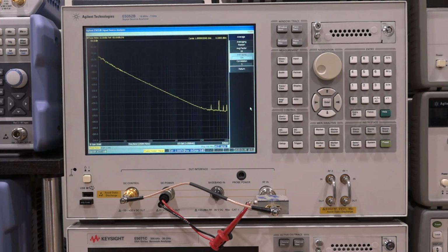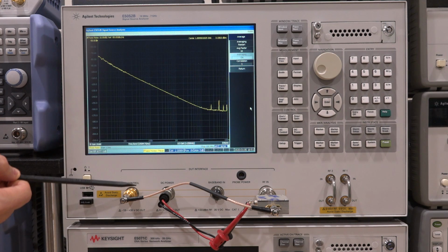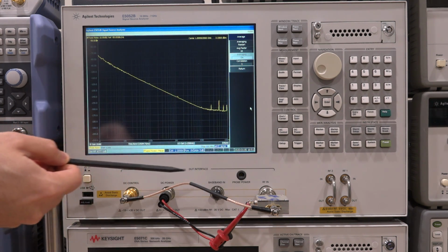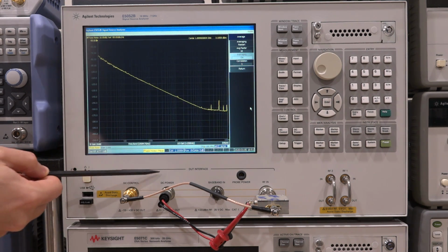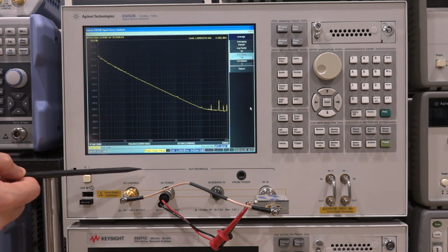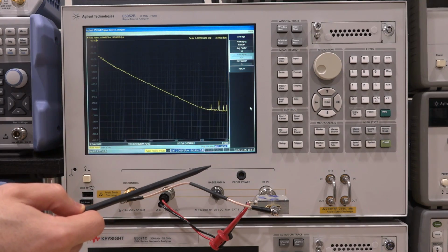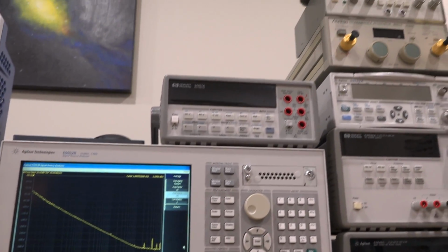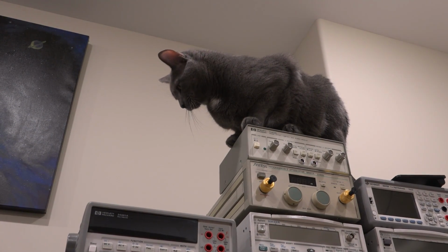So here's our VCO measurement setup, which is a little different. The VCO is directly connected to the input of the instrument from here, but the VCO control voltage is controlled by the DC control of the E5052, and the VDD of the VCO is also controlled by the DC power. Both the DC control and DC power are ultra low noise in order to not pollute the signal coming from a sensitive VCO. And of course, there's the digital PLL, which can lock this VCO and give us very precise measurements. At the same time, we always have CAT scan. He's always watching, making sure the measurements are correct.